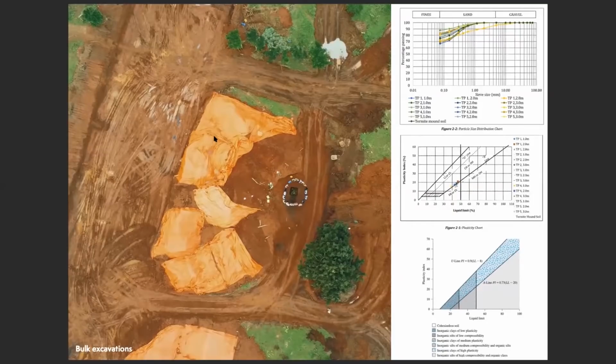one of the first charts really shows we dug many different holes and characterized our soil there in that chart. Most of the pits really showed that we have a lot of silt and very, very little sand, really 10 to 20% sand, and the rest being silt and some little clay.